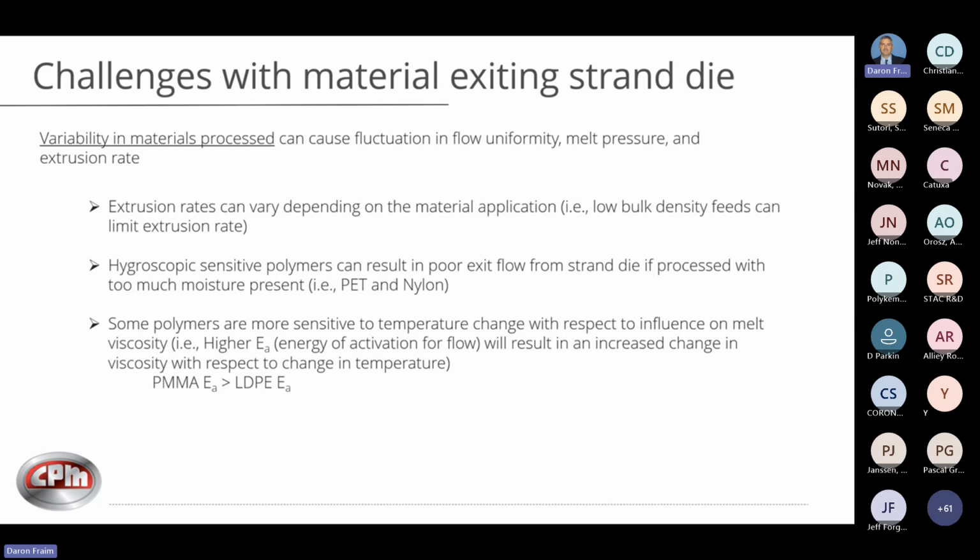Your hygroscopics like PET and nylons, if those are processed undried, a lot of times the moisture can be an issue and cause some poor exit flow from that strand die. And as I mentioned, some polymers are more sensitive to temperature change.